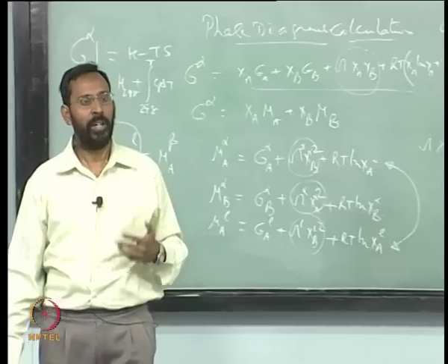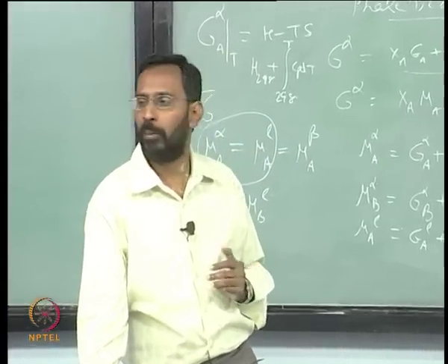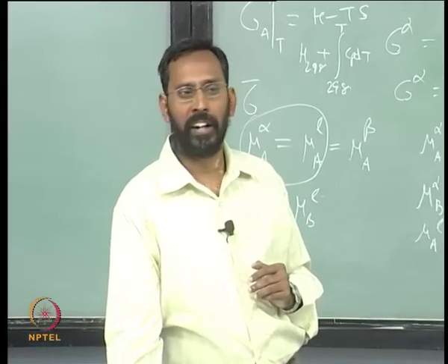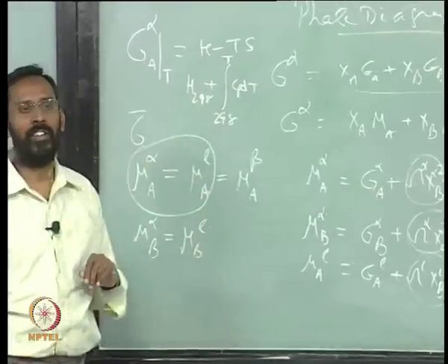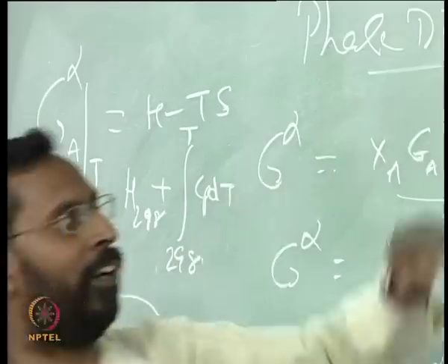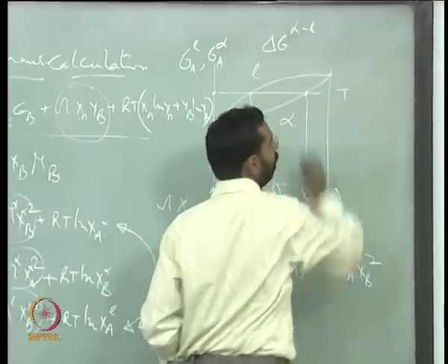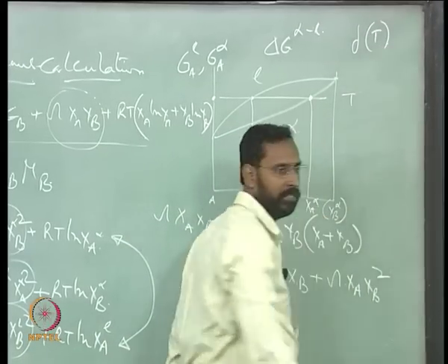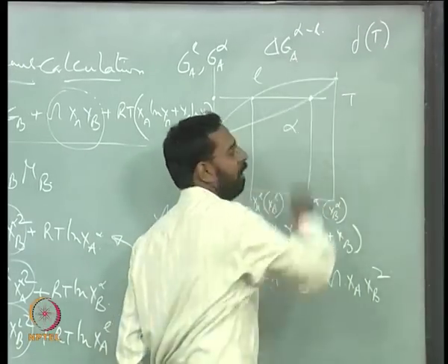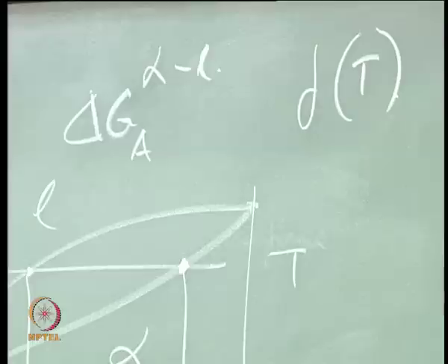That is where you need to use various thermodynamic models that are available, which we talked about in one of the classes, where we talk about the change in the free energy between alpha and liquid. If I know delta G from alpha to liquid as a function of temperature for a given metal A by some model, where there are various models. One such model is Turnbull's model.